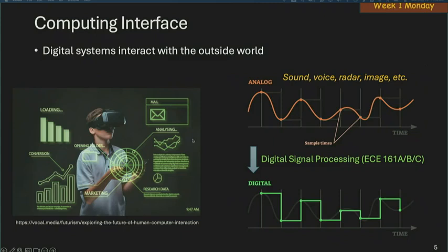And this class talks about digital signals. So analog signal is continuous in time and continuous in value. Digital signal does some sampling, so we only remember the value at certain time instances. And it also does some quantization by converting that continuous magnitude into a fixed bit format. And you can sample it at every second, 10 times every second, 1,000 times every second, depending on your sampling frequency. You can store each magnitude using 1 bit, 2 bit, 10 bit, 1,000 bit, whatever number of bits you like. But that is a digital storage format where everything is stored as a series of zeros and ones.